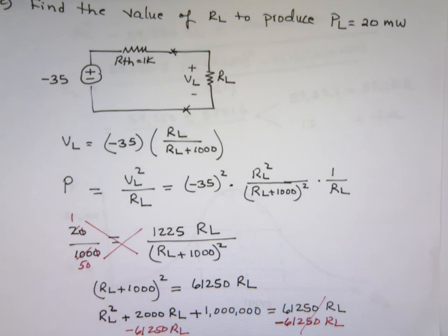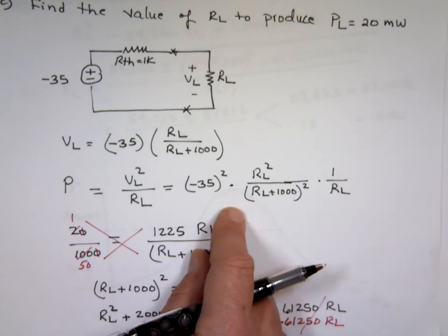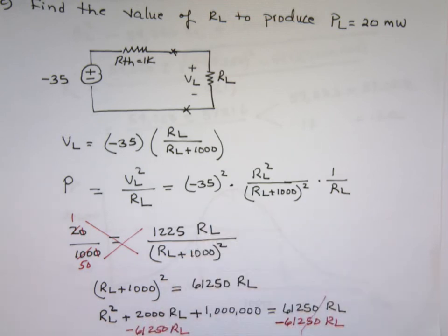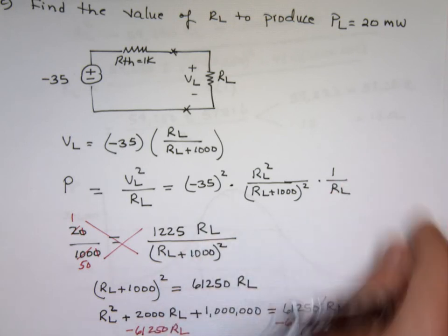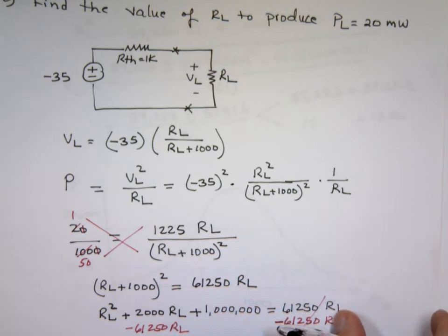Take this equation, plot it as R sub L goes from 0 to, I don't know, 60,000, and see what will happen. Plot the power, and you'll see it will look like the curve we just graphed there. I might do that if I have time today, and I'll bring it next time. Plot it in MATLAB, takes 2 seconds, set up a loop there. R equals 0, incremented by 100 to 60,000, plot that, R sub L versus the power.